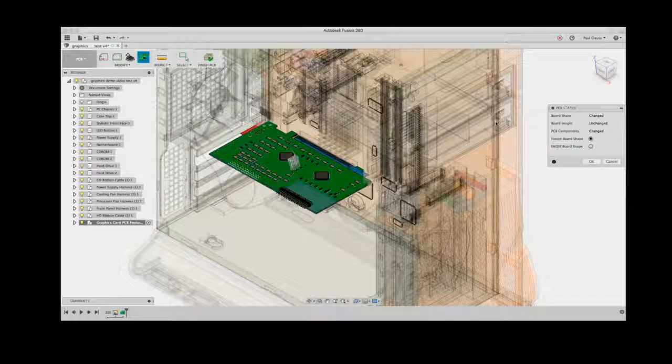He'll get the notification that there's a movement. I'll pull that in. I'll see the traces kind of all crisscross, but now I could rip it up. That way I could do my trace and accommodate the component according to its new placement. That way I could generate those paths, okay? And will Eagle automatically generate new paths if I move it? No, so in Eagle, it's called rip up. You've got to rip up those traces and turn them back into air wire signals, and then invoke manual routing or the autorouter. That way those traces can now be defined.